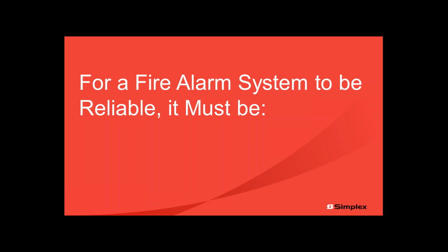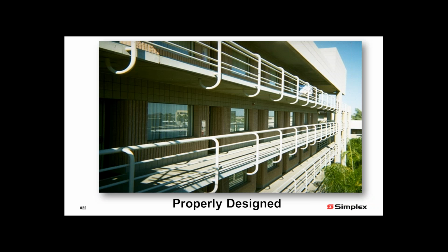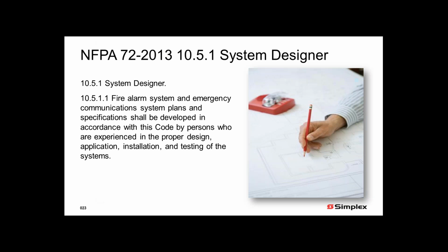So when we look at fire alarm systems, we talk about reliability. Is it going to work when we need it to work? So we say for reliability, it must be properly designed, meaning if we have an outside area like this, I don't know if you can see my mouse, but there's an audio-visual unit right here. Is that enough of an audio-visual unit to get the people's attention in all of these rooms? Is it the right device to have outside? So we've got to make sure our devices and systems are properly designed before they're even installed. We can negate a lot of nuisance alarms or problematic situations by having a system that's properly designed.